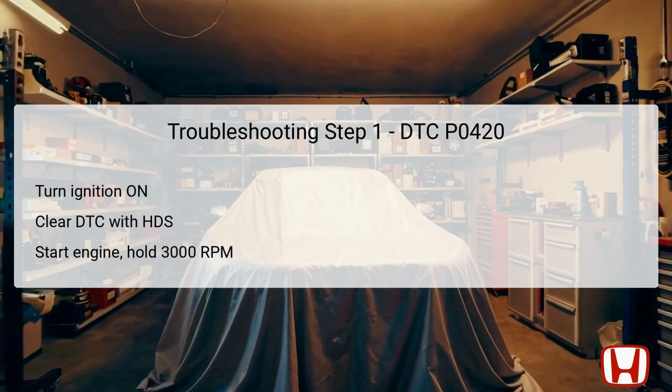This procedure helps in bringing the engine and exhaust systems to operating temperature and allows the radiator fan to engage. Monitoring the OBD status is pivotal after these preliminary steps to check if the P0420 code persists.